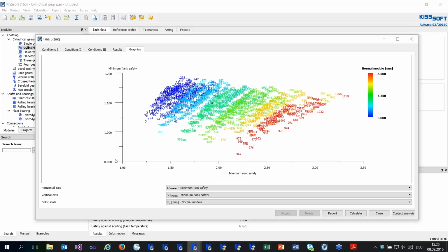And a similar thing applies for the flank. We are from 0.95 up to 1.2 flank safeties, and remember, flank safety is based on Hertzian pressure law, and that means if you change the safety from 1 to 1.1, maybe, so 10%, it means in torque capacity 20%. So from here to here we have more than 30% increase, and that means we have about 60% more torque capacity. Not as much more as in the bending line here, but still it's a lot.